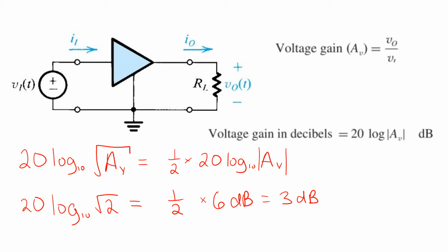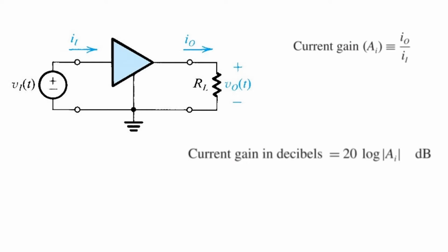Finally, recognize that if you have the voltage gain in dB, you can always convert it back into the original volts per volt by dividing by 20 and raising it all to the power of 10. That'll give you the magnitude of the voltage gain in units of volts per volt. dB can also be used to express current gains, that is the ratio of an output to an input current, which would normally have gains of amps per amp, but still that's a dimensionless quantity, so we can express it on a logarithmic scale by taking 20 log base 10 of the gain in amps per amp.